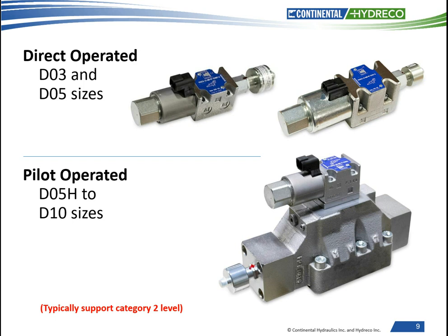We have DIN or Deutsch connections. If you notice in the pictures here, we utilize a covered manual override to prevent manual actuation causing an unintended consequence. Again, think the process through. Make sure that nothing can happen if it's not meant to happen.